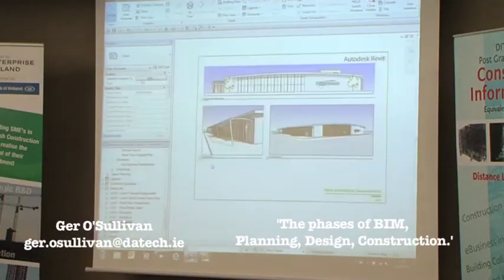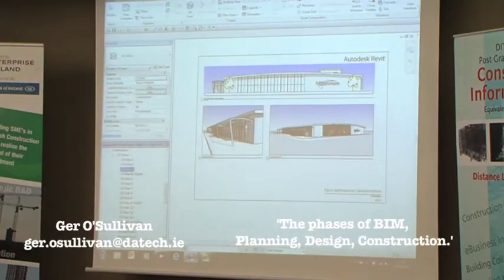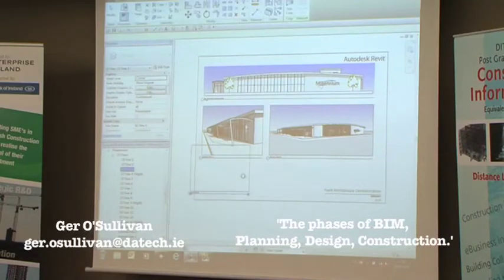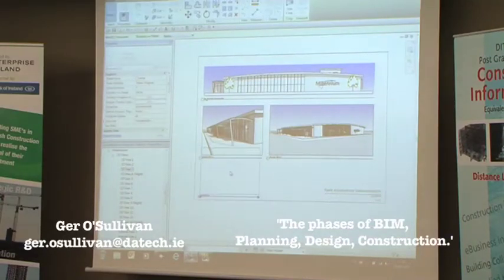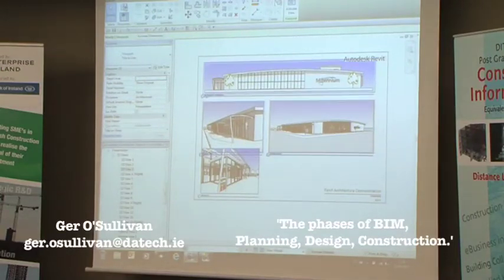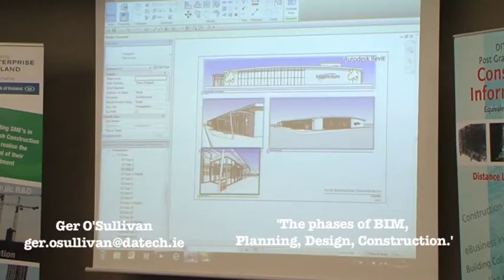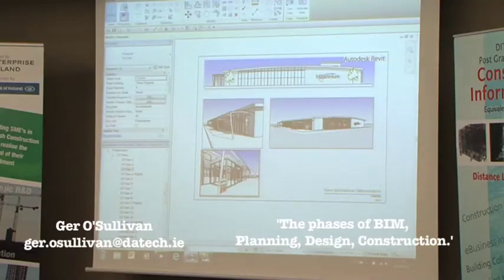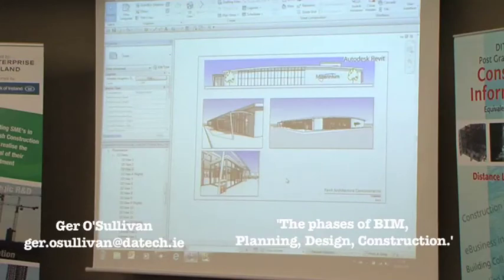Again, it's my unnamed sheet here, and we'll just pop that view in. I think it's this one, number 3. Now if it is a little bit too big, we can always move the views around afterwards. I think that is the right one. If you say that's a little bit too big, let's just move the views. This is just standard stuff. We can pop them up like that and they will move around. I'm a little bit tight on space, so we'll do a little cheat. We'll take away the titles, and that will look a little bit better. Okay, so you get the idea. I can very quickly present this to a client or whoever from that model.